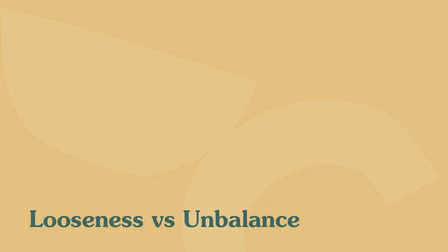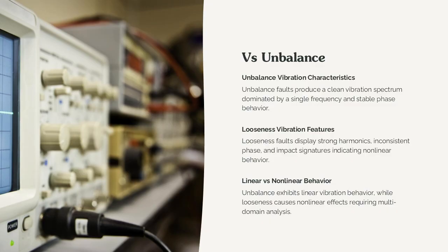Looseness versus unbalance. This slide compares looseness with unbalance, helping analysts avoid common misdiagnosis. While both faults may show elevated one-times vibration, unbalance typically produces a clean spectrum dominated by a single frequency with stable phase.